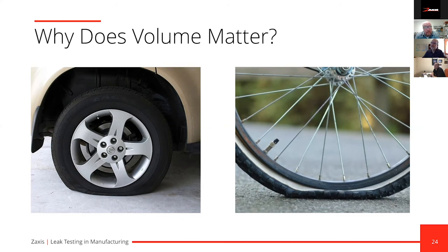So when we say we recommend that you don't have a reject level that is 0.0001, it's because there are external factors that can affect this. If an operator held one part longer than another before they tested it, you could get a different decay reading. If the air conditioning kicked on, lots of different things can affect it that are external to the actual test.